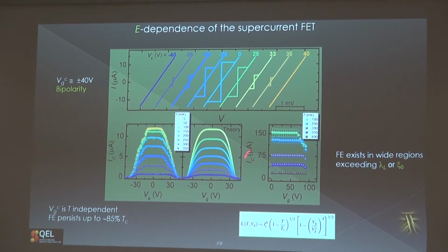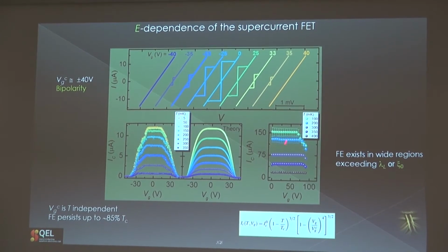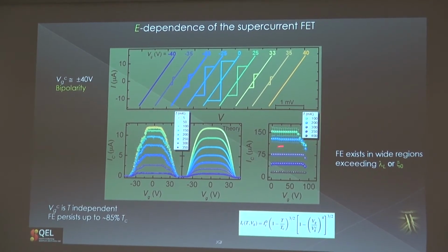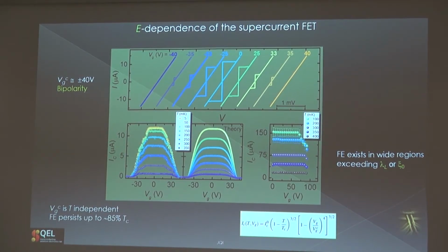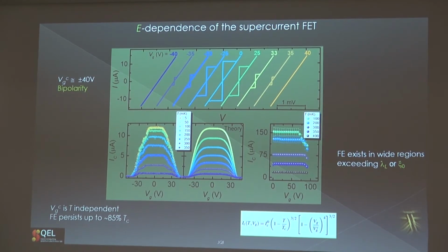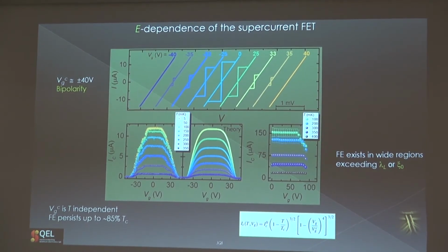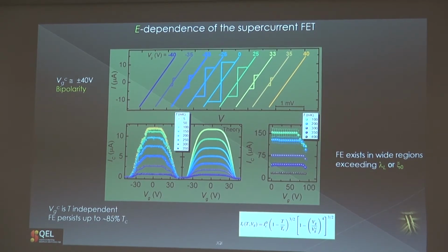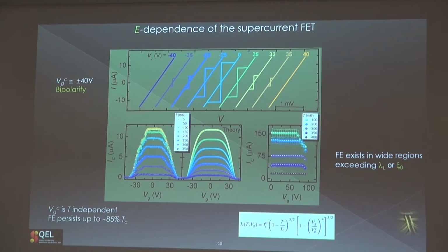And then we apply the backgate. And so you see that in this rectangular shape, we obtain a suppression of the critical current up to 34, 40% of the initial critical current. Of course, here it was applied just with the backgate, with a separation of around 300 nanometers between the backgate and the wire. So the intensity of the field is reduced with respect to the lateral split gates. The field was applied perpendicular to the plane of the metal. So this shows that basically the effect is present also in very large regions.